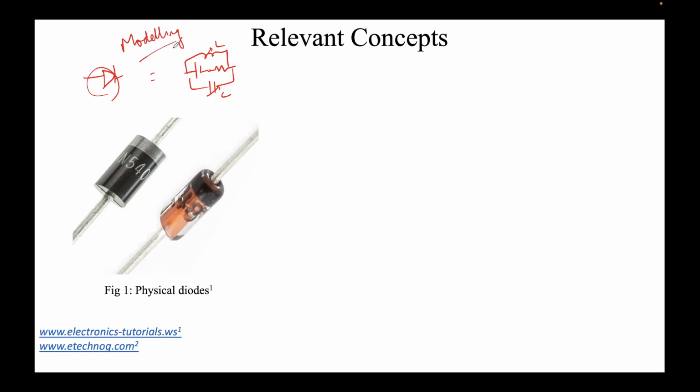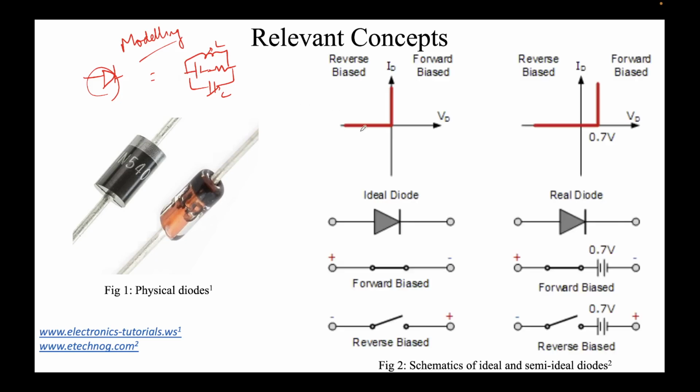And this you will see across, not just for junction diodes. You must have seen this in BJTs, small signal equivalents, FETs, field effect transistors and whatnot. So a very simplistic model is shown here. This is an ideal diode. So it's operating as a switch. When you apply a forward bias, the switch is closed and an infinite amount of current can flow. When it's reverse biased, which is shown here, you can see the polarity has been reversed, the switch is open and no amount of current can flow, which is shown here using zero current, the horizontal line.